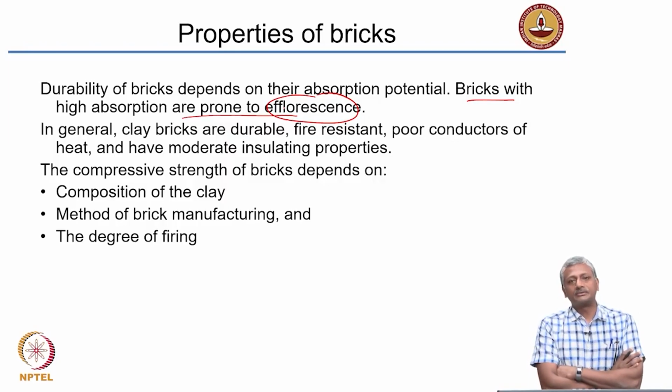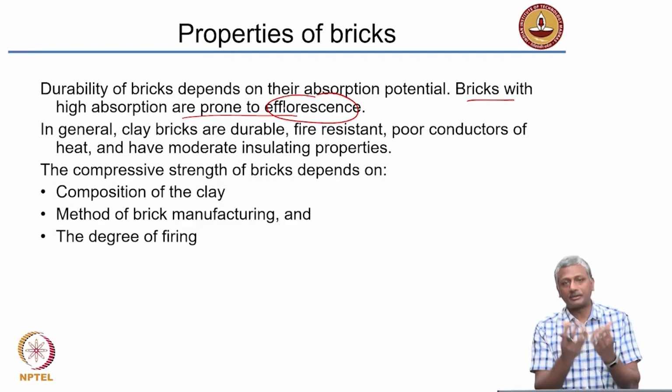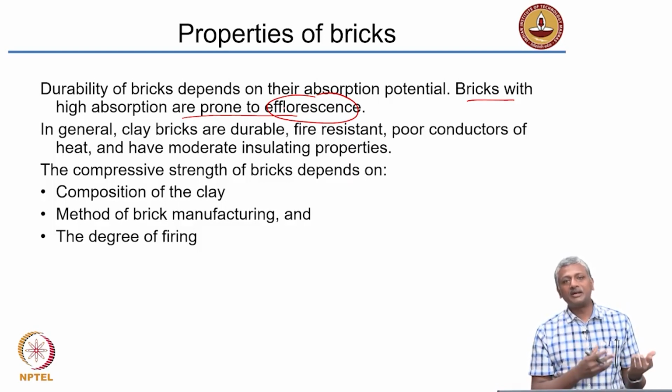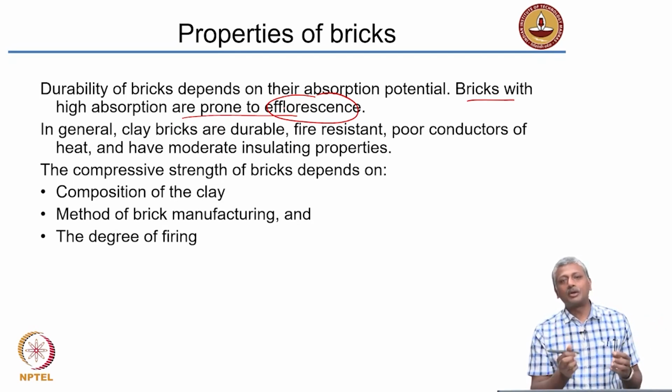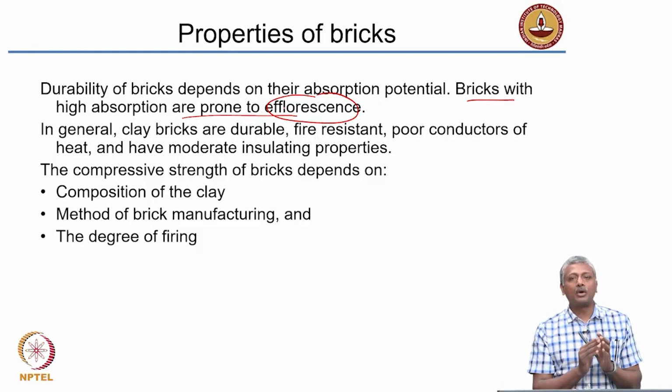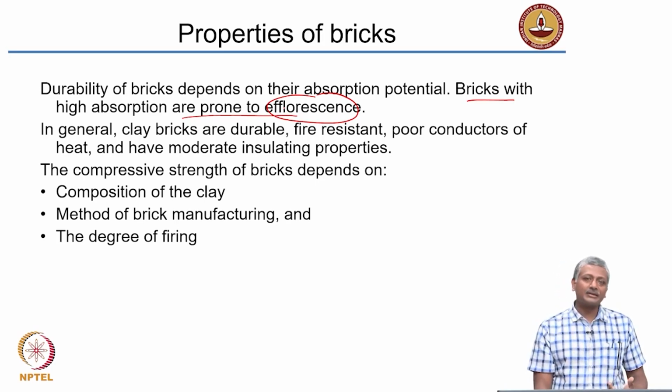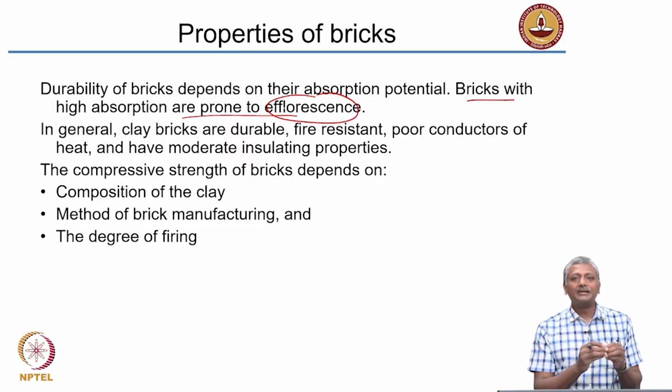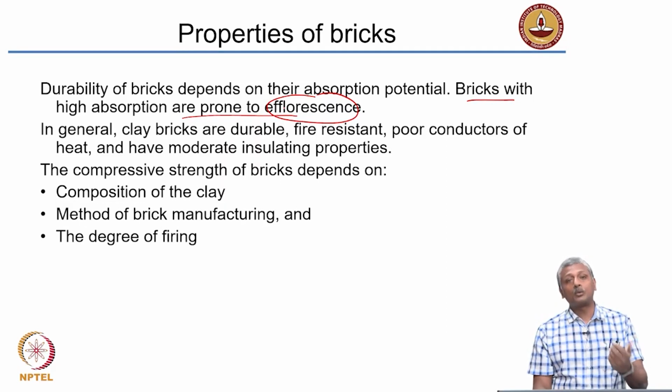What is efflorescence now? Now, the name itself implies that something is flowering. Okay. But in the case of buildings, efflorescence is not necessarily a good thing. Okay. The flowering part that we are talking about are salts that are present either in the brick or in the water that come out on the surface and give the wall a very poor aesthetic quality. Okay. Now, we typically associate flowering with nice quality flowers, right? That is not the case in building. Efflorescence actually means that we are having some salts that are present either in the brick or the water that come up to the surface and then start crystallizing, leading to a very poor aesthetic quality of the surface.